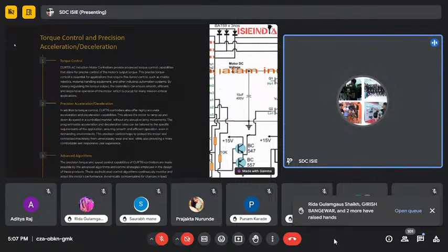Okay, Curtis offers us a programmable function, indirect field orientation control, auto tuning function, dual drive functions, and CAN bus configuration with integrated system controls. So these are the major functions we get with the Curtis controller. You have also seen that forklift. The forklift is very useful and has been widely used for the past 20 years by JCB and forklift OEM manufacturer companies for the pumping and hydraulic system.